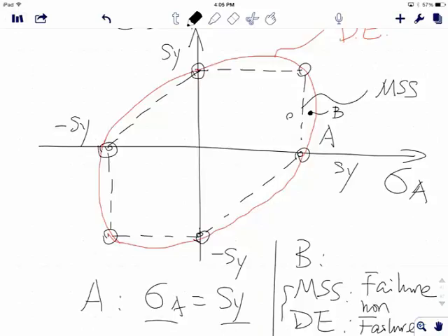Okay, but here's the interesting thing, because like I said, this is for tensile. No, ductile. There's lots of ductile material, alloys, right? Aluminum, or even plastic is a ductile material, right? Lots of ductile material here. Now they did a bunch of testing, depending on different two-axis loadings. They fall in line here. Some of them fall in between, inside of the maximum shear stress. So really, I'm not saying one is better than the other, it depends on the material, all right?